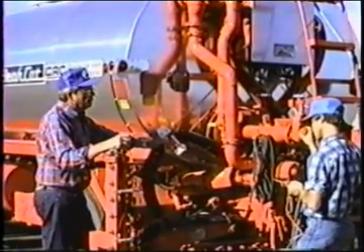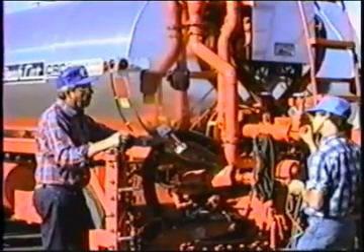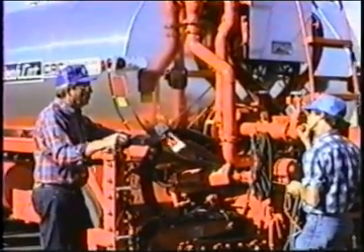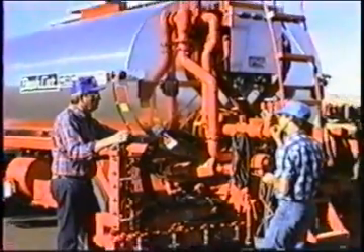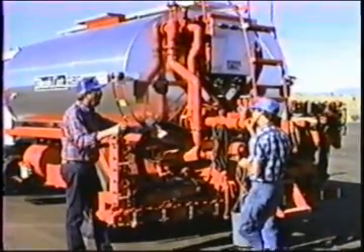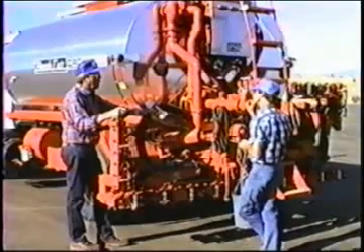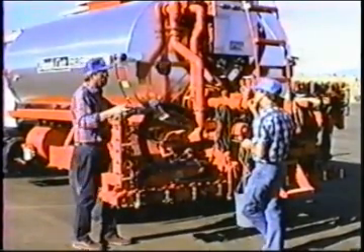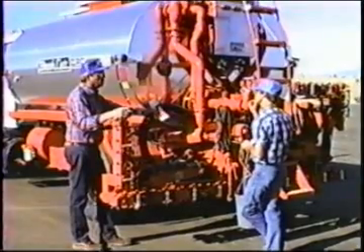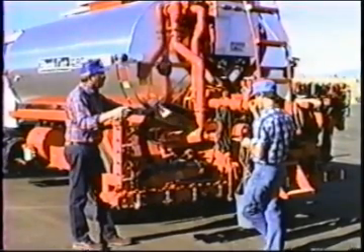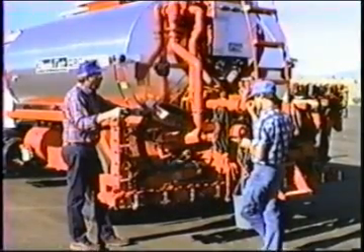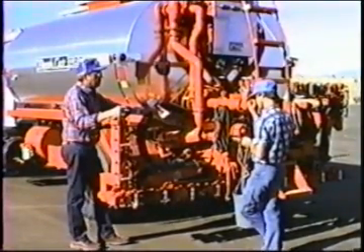If we're shooting a constant width, the most accurate method is the positive displacement. That is where we set the pump at exactly the right speed for the ground speed and bar width, and set the pressure high on the bypass valve. Set it up around 30 pounds so that it's well above what our actual spray bar pressure is that's created by the size of the spray nozzle. Now, does any of that make sense?